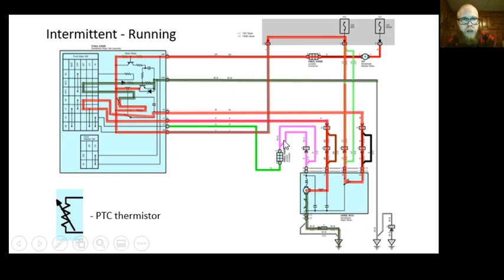All right, but what the pinpoint test would tell you to do for this would not be, look at the diagram and do some electrical education on how transistors and discrete circuits work. It would say, do you have power, or do you have ground here? Do you have power on this wire? Ohm out these wires. Do you have low resistance? Okay, well then it has to be the switch.